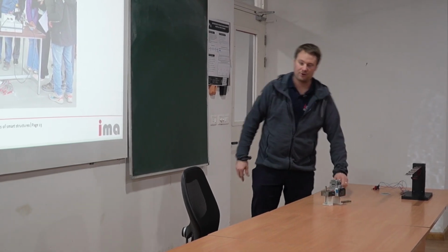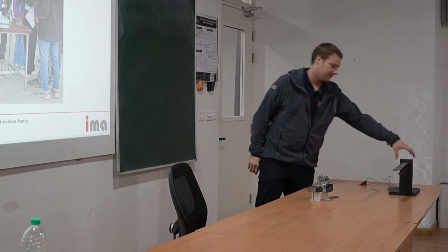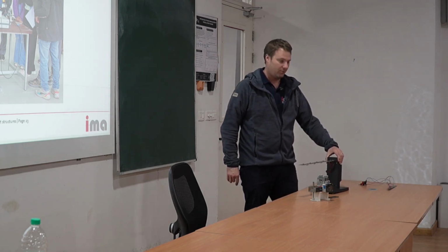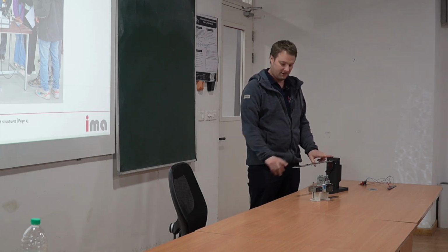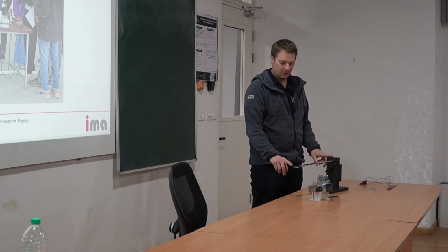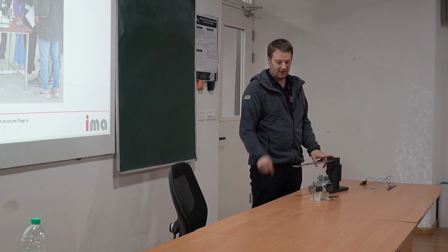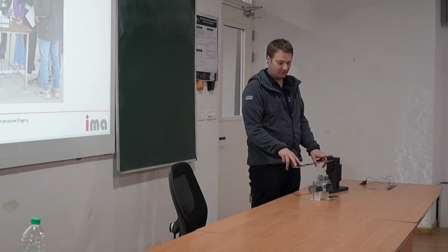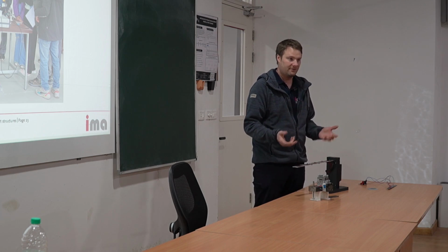You may or may not remember that in all labs we have used piezoelectric material only as actuators, never as sensors, so we use the inverse piezoelectric effect. We never use the direct piezoelectric effect. So, a bit unfortunate today, we could have used the direct piezoelectric effect. What I didn't show you is that if you connect either of those patches, you will immediately see the same thing as the laser distance sensor, because you will see the strain, and the strain will obviously put out the same signal, the same frequencies.